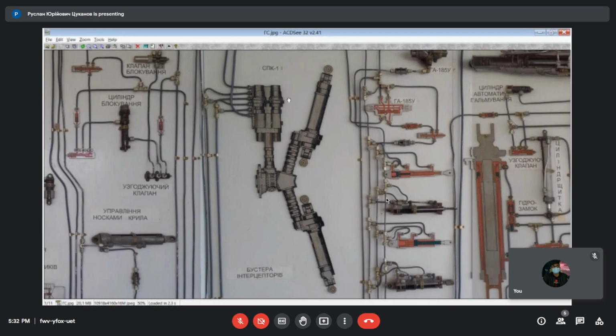So here there is a pair of hydraulic motors. Each hydraulic motor is attached to its own hydraulic system, one to the power control system, the other to the combined system. Next, they are attached to a reduction gearbox, via a differential mechanism. So in case of any one hydraulic system failure, the other will work and provide all the functions, but with twice lower speed.